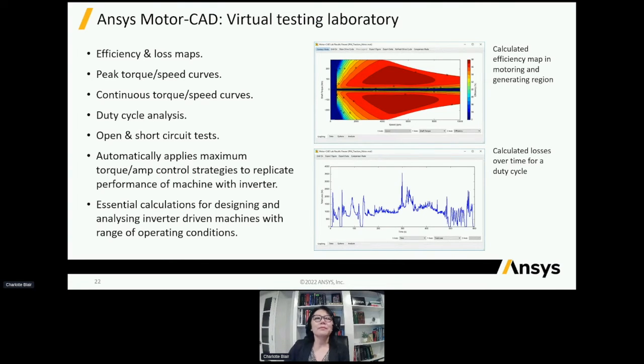And so this plot here will show that wherever it's really red, that's exactly what I want to see. So part of our engineering application education is to say, how do I read this plot? If this were torque and efficiency, I could say, well, at this point here I could go up to this speed, but it's maybe this efficient. So we can read these efficiency plots and say this device will work well and be efficient up to this speed.